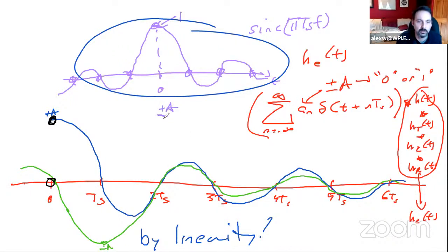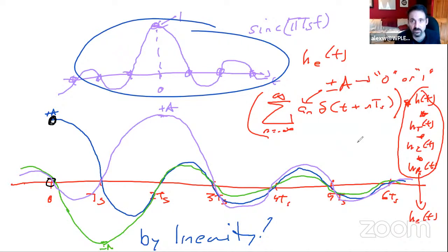So that's going to look like it passes through that zero crossing, that zero crossing, and then here passes through that zero crossing, that zero crossing, that zero crossing, that zero crossing, right? So the zero crossings are critical, except for the desired sample, which will be non-zero at the correct sampling instant. Everything else is going to be zero. So that's zero ISI.